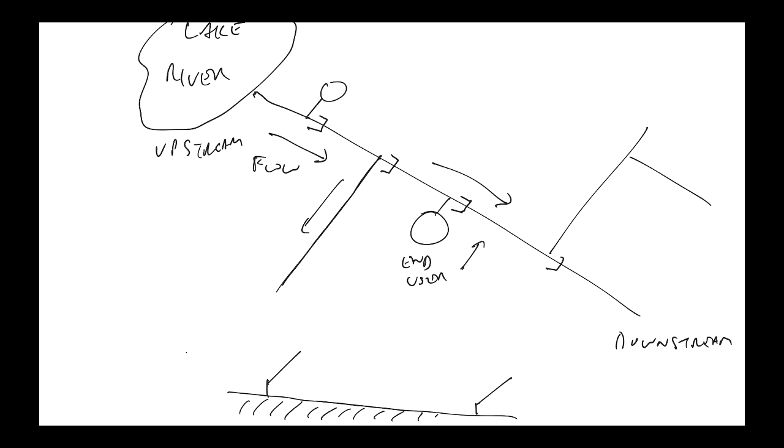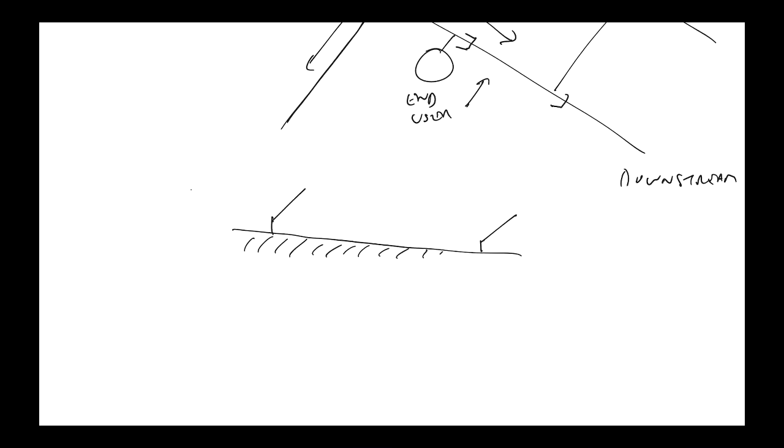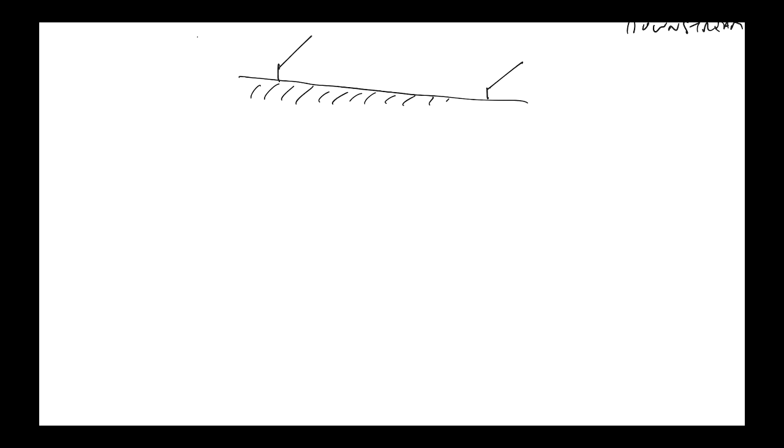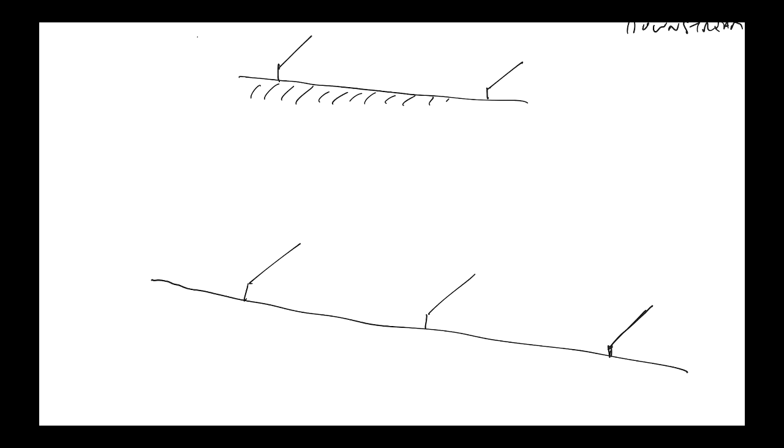So the control system in place at the lowest level, and there's actually a hierarchy of control, but we're just going to look at the control system at the lowest level, results in demand-driven release of water from the source. And it works like this. So we've got an irrigation channel. It's an open water channel of the kind that you saw in the video. Along the channel, there are these regulating structures that can be adjusted. And the way they're adjusted is under the action of feedback control.